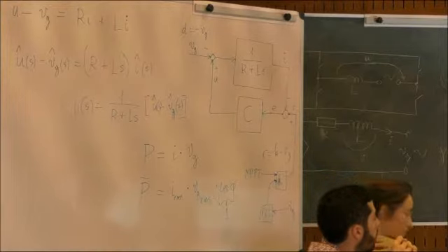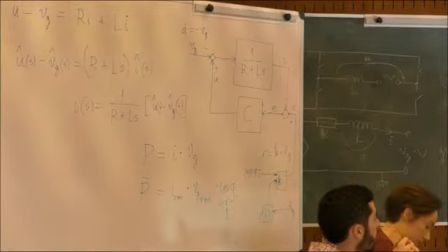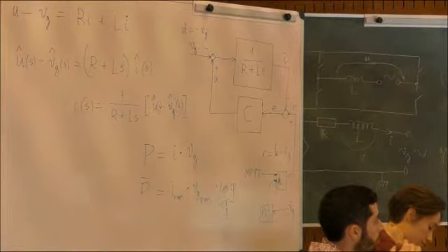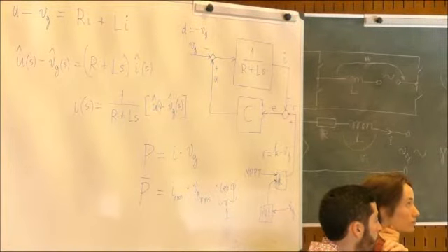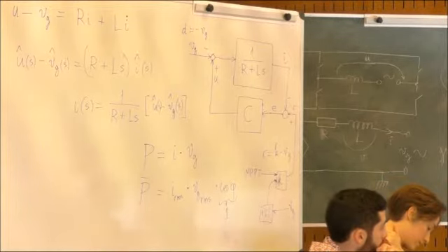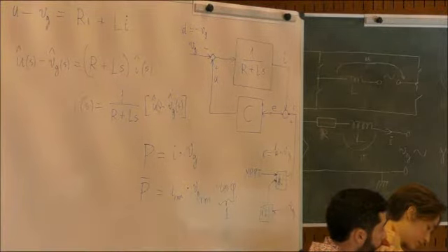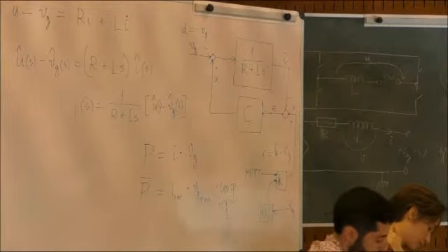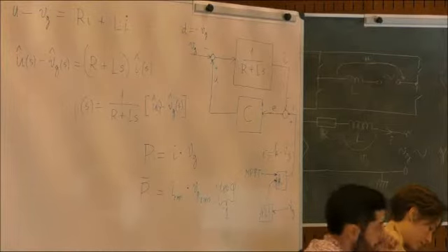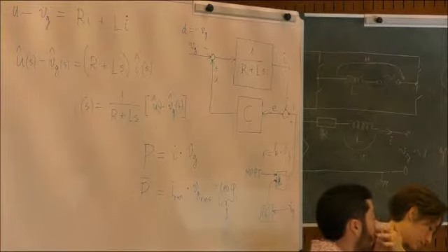It's a disturbance which acts on your flexible robot, and it is very important to say you know the frequency of the disturbance. If you know the frequency of the disturbance, then you want to eliminate its effects, meaning that you want to create a controller with an internal model, hopefully, so a controller with poles at the relevant frequency, so that the effect of the disturbance, which comes at a known frequency, is eliminated.